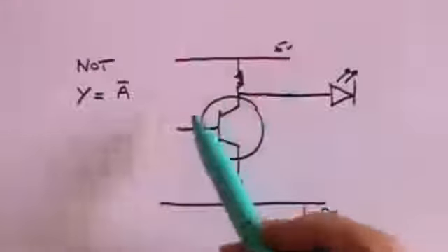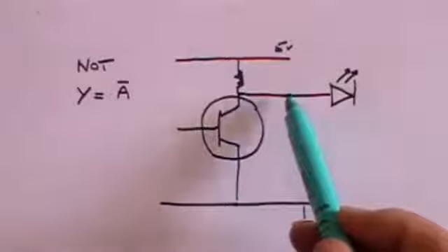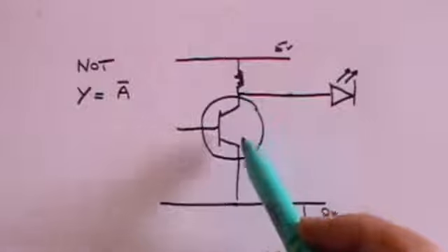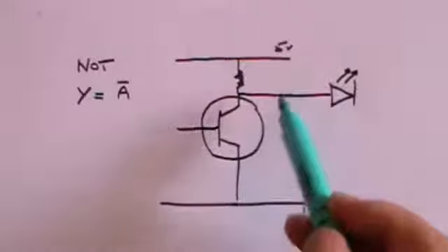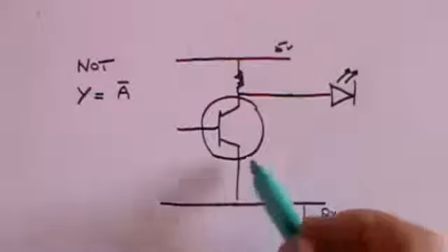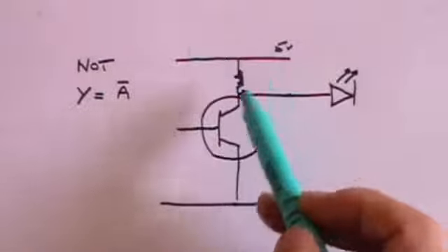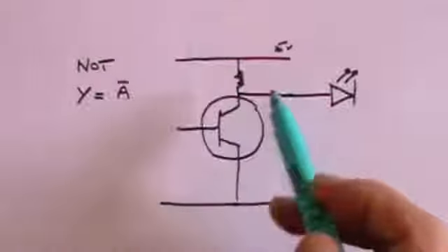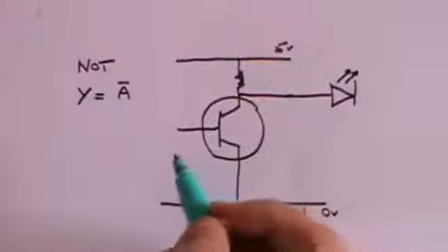And so you've now got a positive voltage on the base, the input, but now no voltage on the output because a current is flowing through here, and so essentially this and this are at the same potential, and that potential is 0, and the whole 5 volts is dropped across the resistance here.